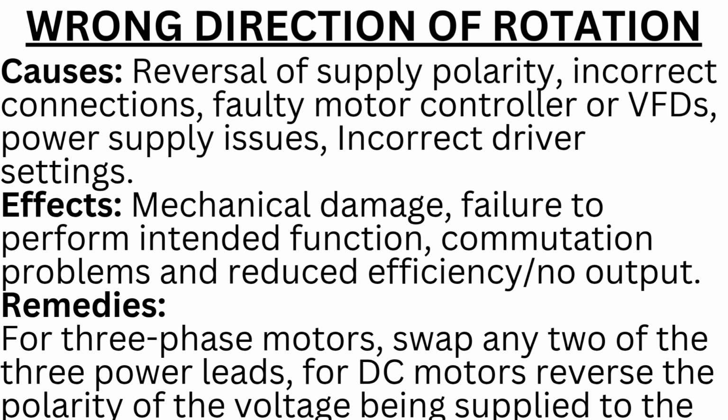Causes. Reversal of supply polarity, incorrect connections, faulty motor controller or VFDs, power supply issues, incorrect driver settings. Effects. Mechanical damage, failure to perform intended function, commutation problems and reduced efficiency or no output. Remedies. For 3-phase motors, swap any 2 of the 3 power leads.